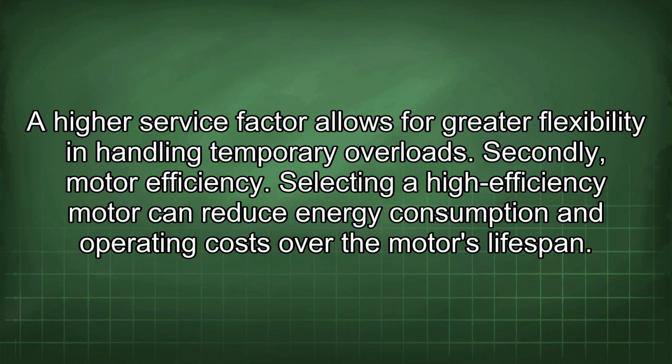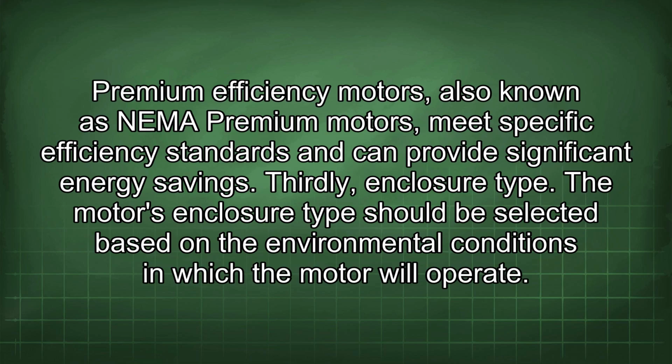Secondly, motor efficiency. Selecting a high-efficiency motor can reduce energy consumption and operating costs over the motor's lifespan. Premium efficiency motors, also known as NEMA Premium motors, meet specific efficiency standards and can provide significant energy savings.